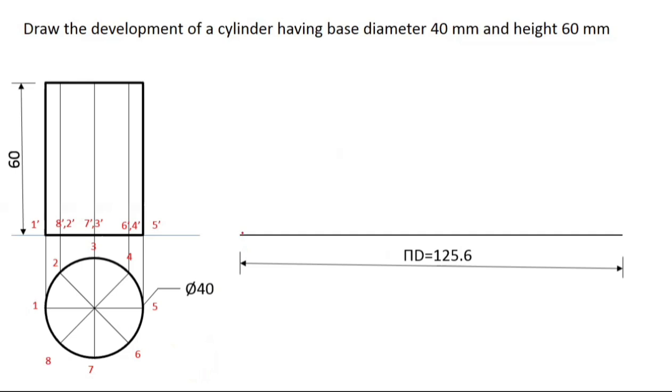You have to draw a line at any angle and at any length. Remember this thing. This angle is up to you how much you are going to take, 30, 40, 60. It doesn't matter. Later on, take a compass and open any length, whatever it is, 10, 20, 30 mm, it's up to you. Open the compass and put the needle over here and divide first, second, third, fourth, fifth, sixth, seventh and eighth.